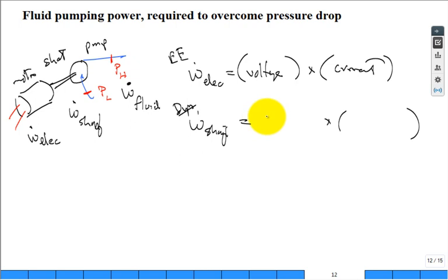It's the torque in the shaft. If it's got no torque from one end to the other end, it's not transmitting any power. It's got that rotational torque, okay? Times the rotational speed.